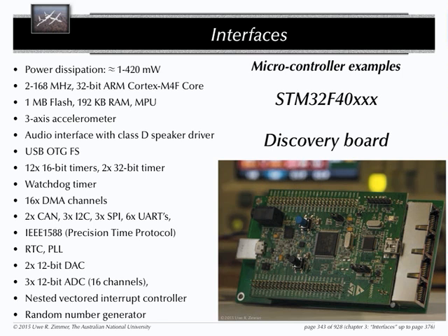What you have on that board is also an audio interface with a Class D speaker driver directly on the board itself. It means you can plug in a headphone directly. You have a USB on-the-go interface on that directly. Tons of watchdog timers, two 32-bit timers, 16 DMA channels.